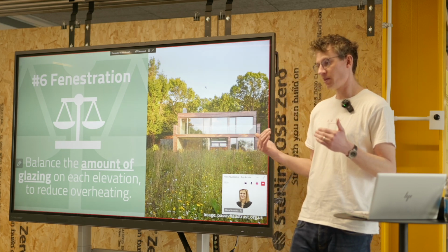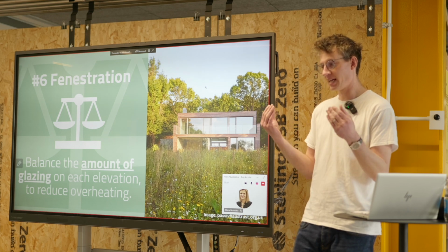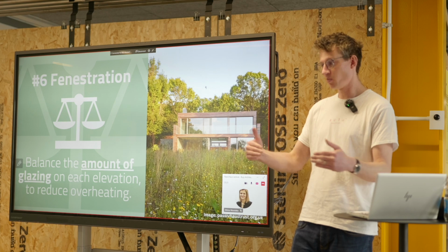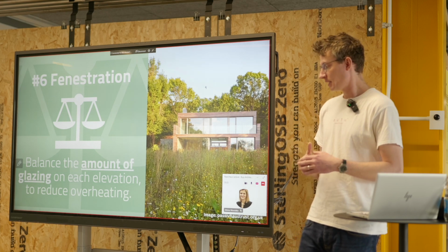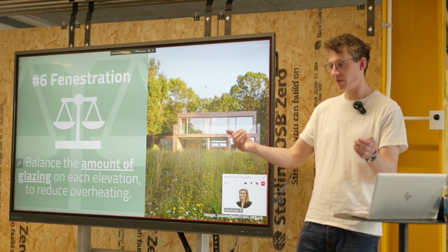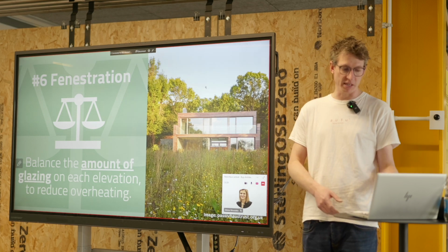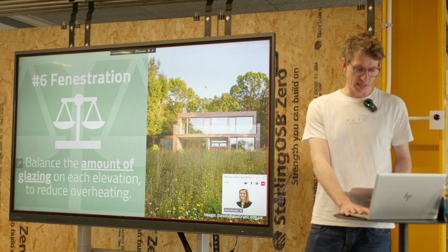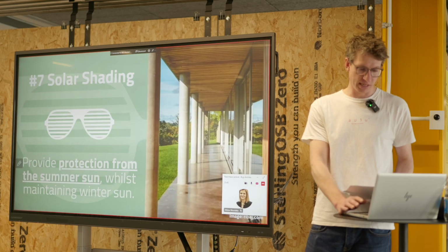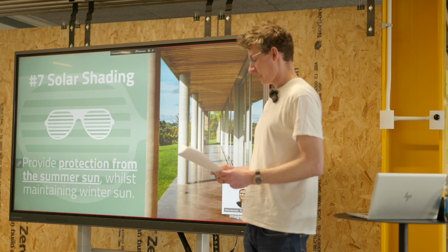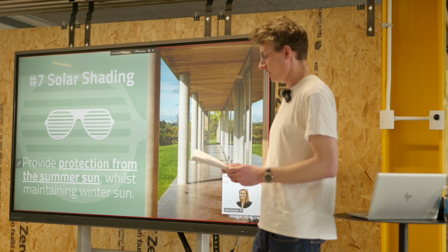So it's important to consider your windows as a line of insulation, and those windows should be sat ideally within the insulation layer, so that you've got a very consistent line. You're not stepping in or stepping out, otherwise you get cold bridges, those cold spots coming around the edge of the windows. So it's a really important technical detail that is being improved, shall we say, with more time. But there's lots of builders out there that struggle to embrace these changes.